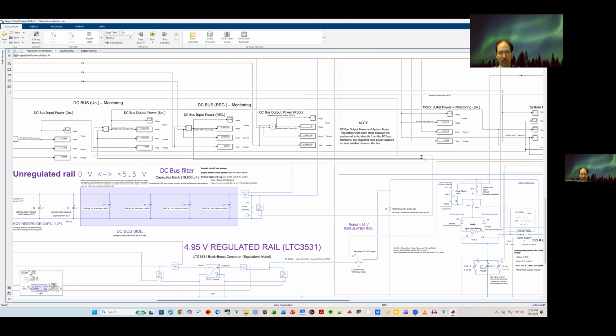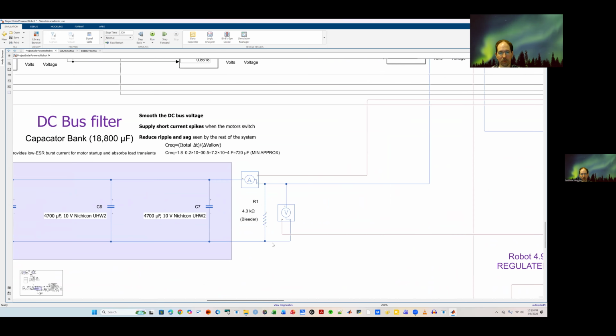So basically, once you finish that, then I added a bleeder resistor so that when the circuit is powered off, it will discharge and won't stay charged, to protect people from handling it and getting shocked. So basically, it slowly dissipates eventually. And I set it at 4.3 specifically because that was the time constant that I wanted. It came to be like 1.2 days or something, but then I added more capacitance, and I don't know if I changed this or I did. I think I changed it once, but I didn't bother changing a second time.